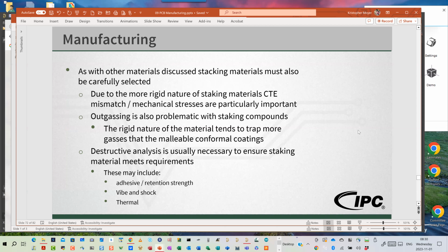But yes, as Edson says, all materials have a dielectric. So if you have any dielectric concerns, then take that into account when you are applying your materials to the boards. As Edson said, if you happen to have RF structures on your board, such as antennas for Wi-Fi or Bluetooth that happen to be running in the RF spectrum, you may need to mask and keep those areas clear of the conformal coating so that you do not alter or affect the behavior of your antenna structure or your RF structures.